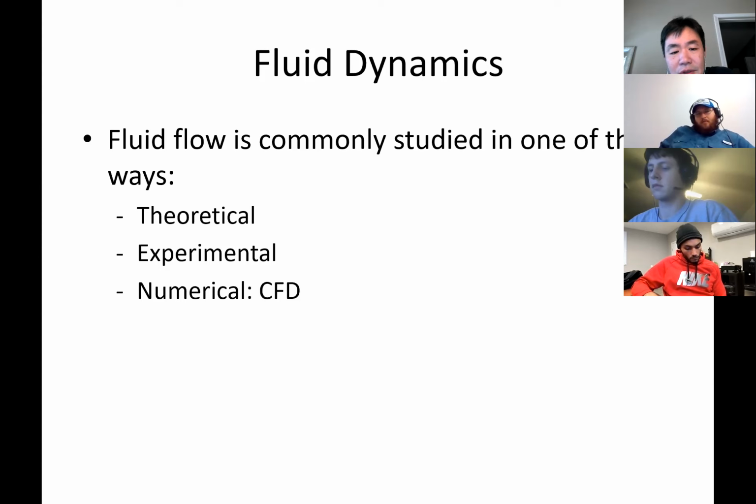So what numerical CFD does is we actually use a computer, not really solving the governing equation. We approximate the equation. We simplify the equation into a matrix, linear equations. The differential equations are not linear equations, but if we divide our domain into small elements, infinitely small, we can assume on those infinitely small elements the flow is linear. If it's linear, we can use linear equations to represent the differential equation. Basically, that's the idea of CFD.